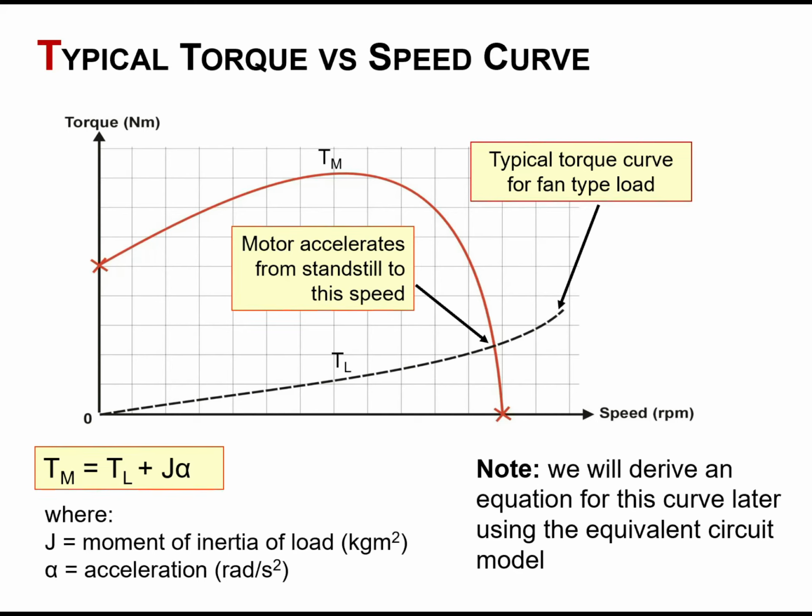So now we will notice that we are talking about different torques. So there is the motor torque, the load torque, and something that is called the acceleration torque. As opposed to the load torque, which is constant, the acceleration torque is the required torque to accelerate or decelerate an inertial load up to its target speed. It is only present when accelerating or decelerating an inertial load.